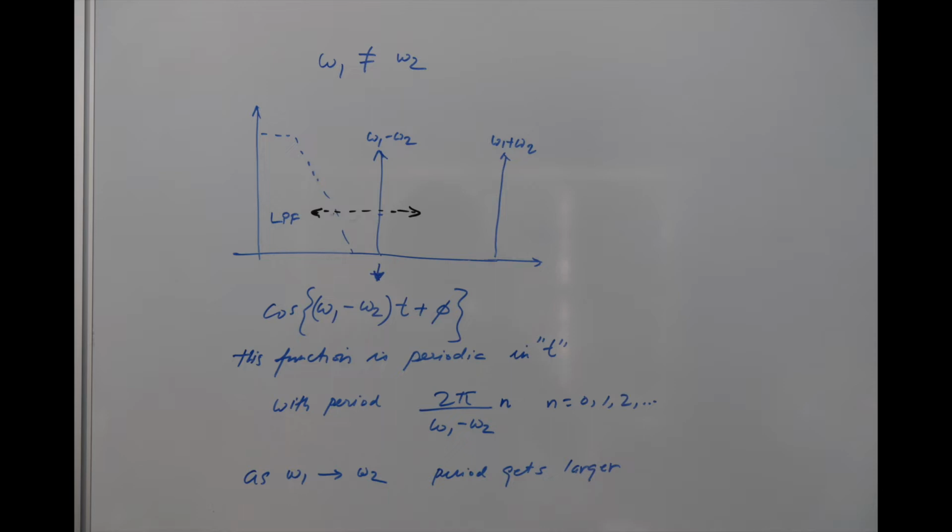You will see a sinusoidal representation which repeats with the period given by 2 pi divided by omega 1 minus omega 2. So that is going to be the challenge in rejection of noise which occurs very close to the frequency of interest, and that's where the selection of the time constant for the filters becomes very, very critical.